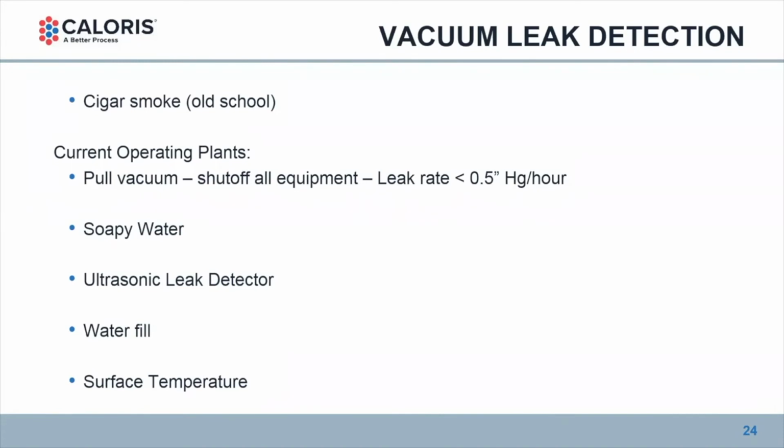They require some training to use properly, particularly in a loud TVR evaporator process room where it can be hard to hear much of anything. You need to be very focused in using the device to find those leak spots. But it's surprisingly effective. When somebody knows how to use one, they can go around and routinely look for leaks.